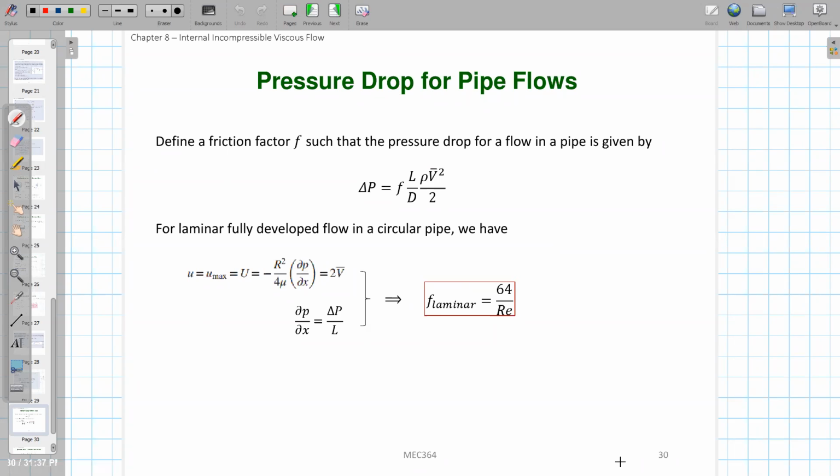And how do we calculate or measure that pressure drop? It's definitely determined by the wall conditions, because this is the friction between the pipe wall and the fluid. If the inside wall is very smooth, not very rough, so the roughness is small, then we know that delta P will usually be small. The pressure drop will not be that big.